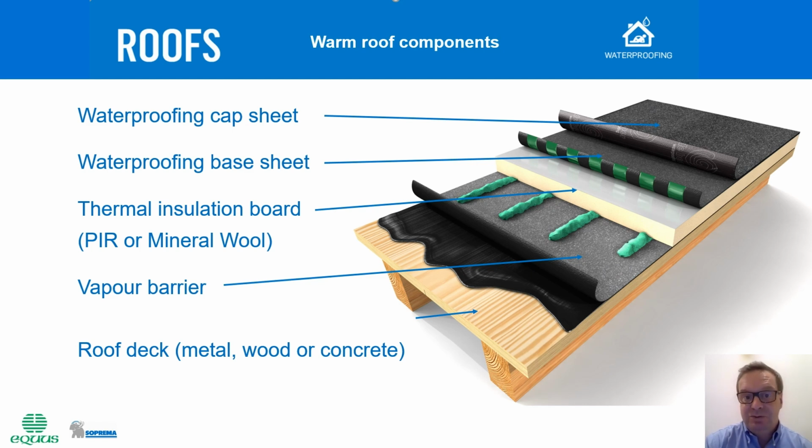On top of the structural deck, we have a vapor control layer or vapor barrier. On top of the vapor barrier, we have the thermal insulation boards. And finally, those thermal insulation boards are protected by a waterproofing membrane system.